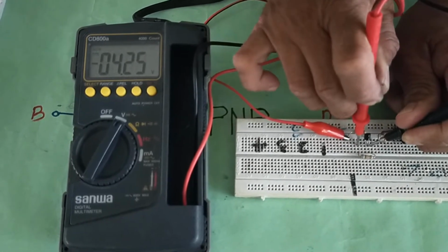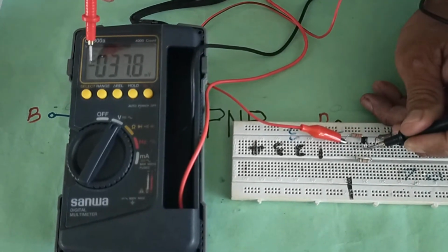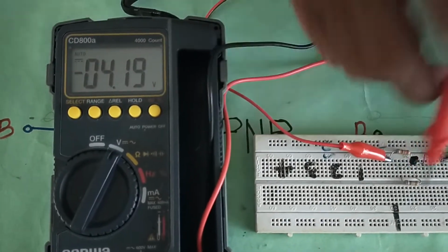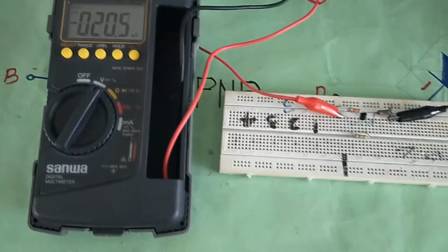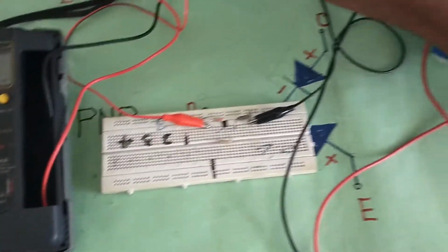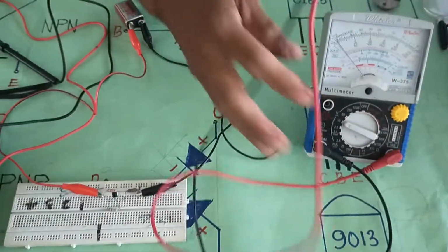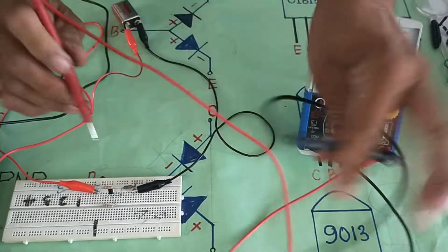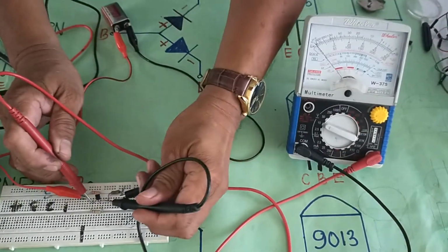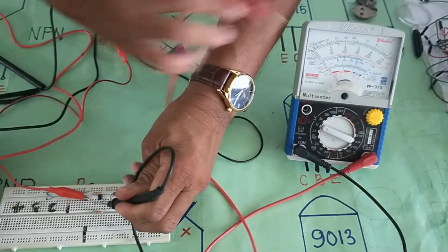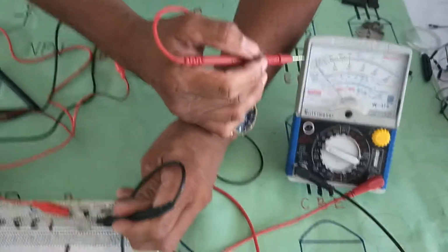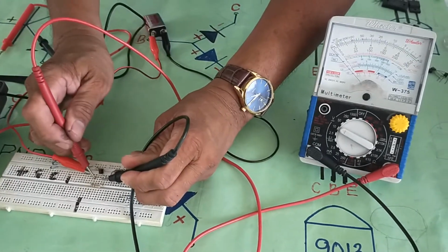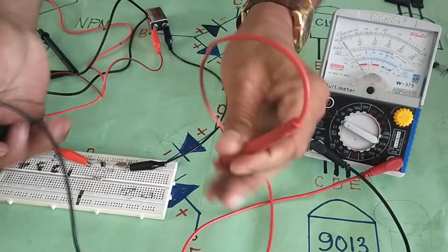Reverse because it is negative. Actually, we have the negative symbol here, meaning to say it is of opposite polarity. Because when we use an analog multimeter, base to collector, the pointer kicks back and moves in the opposite direction. It is not forward. It should be like this.